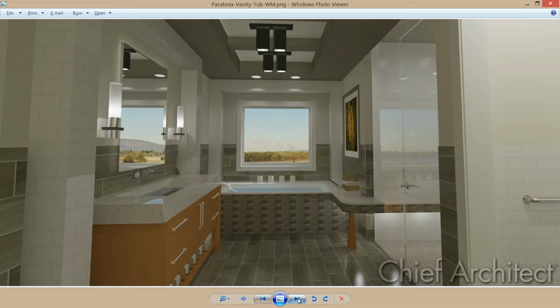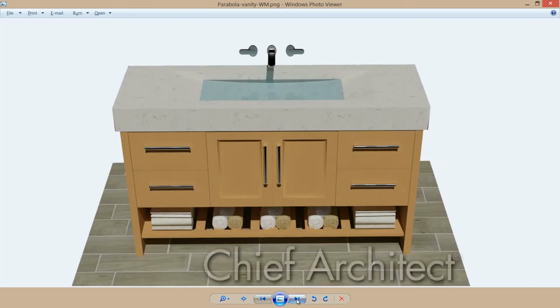You can see the lighting actually underneath that shower bench and how that looks. On the right hand side over here, where actually the water closet's located, I've opened the door. That's a setting that you can click on the door under the options panel and just say render is open. Let's see what else I have here. And then what I've done here is I just copied my vanity sink out and rendered it as a separate object so I can show that specific element for the design.